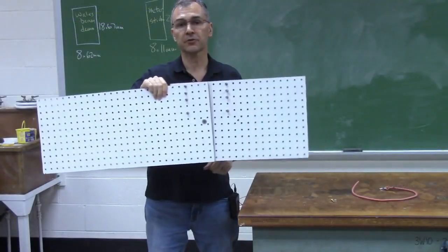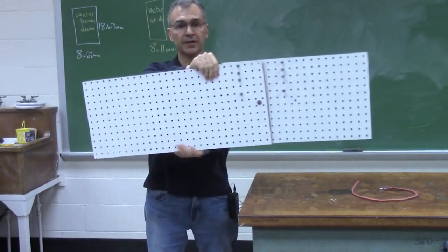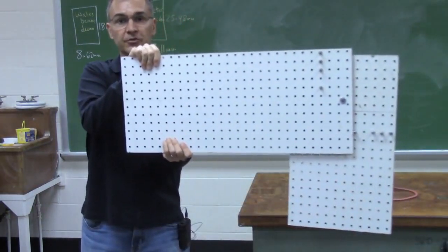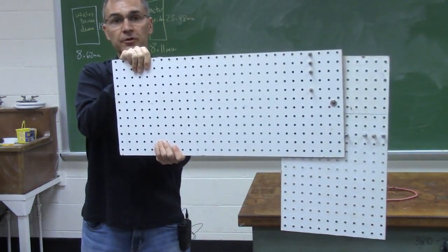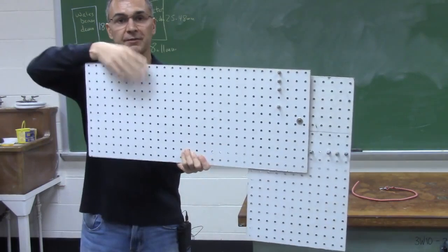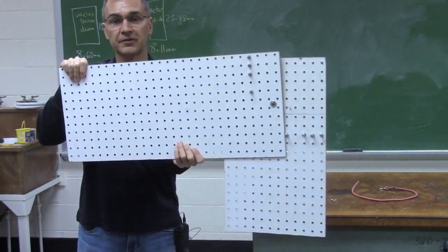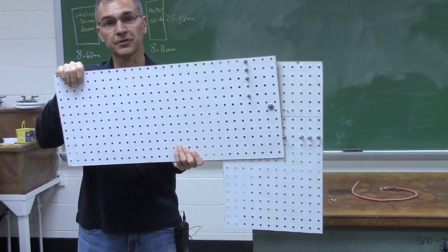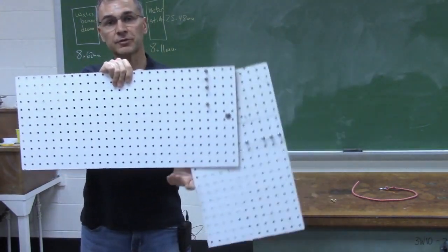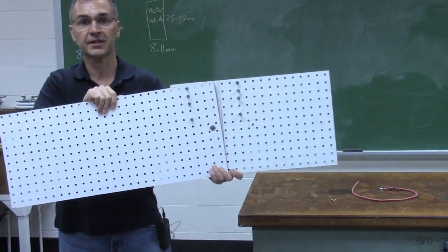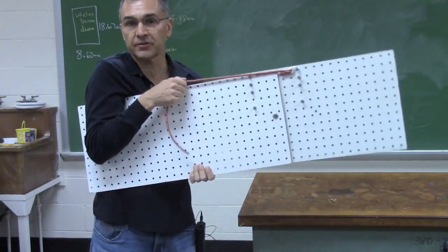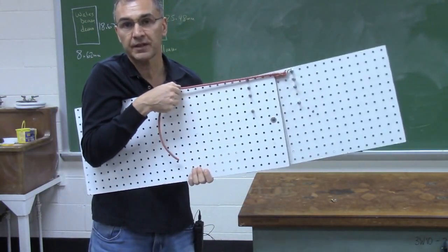One point that we made earlier that we can make again now is, if I have two sides of a beam and a section here, the near end needs to exert not only a force but also a torque to hold up the far end. You can see, here I am, the near end, I'm exerting a force on the far end. That's enough to keep it from falling to the ground, but it's not enough to keep it straight or nearly straight, to keep it from pivoting like this. I need a torque, and that torque is provided, in the case of a cantilever, by the tension in the upper fibers and the compression in the lower fibers.